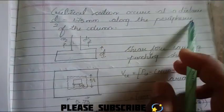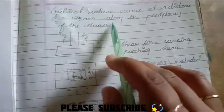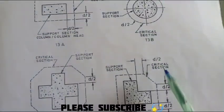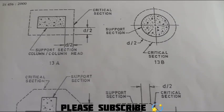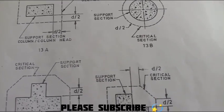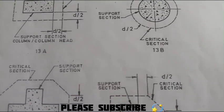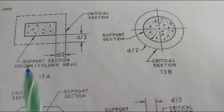The critical section occurs at a distance d by 2. D by 2 is nothing but the effective depth divided by 2 along the periphery of the column. As per the IS codal provision, this is on page number 58. Remember, the table we used for calculating the tau c value is Table 19 of IS 456. And here, as you can see, it is on page number 58.